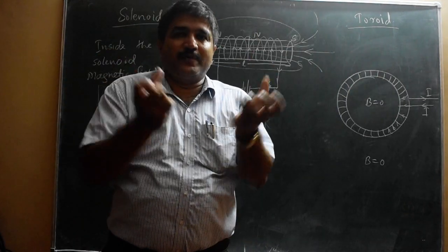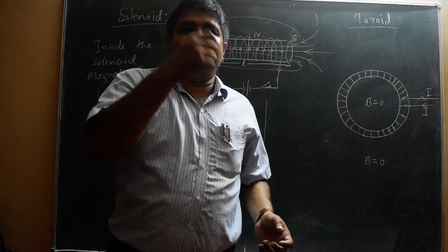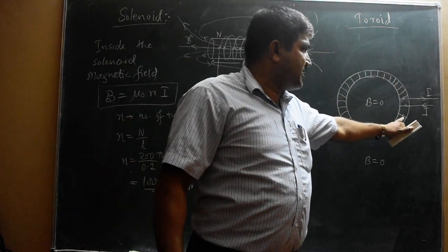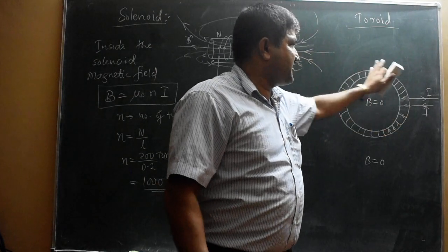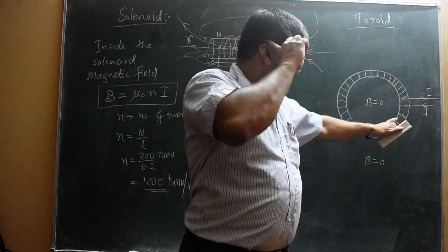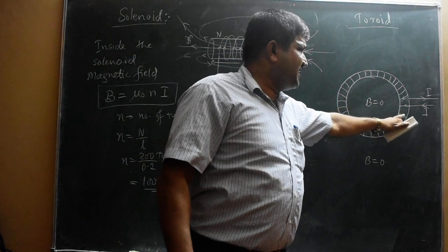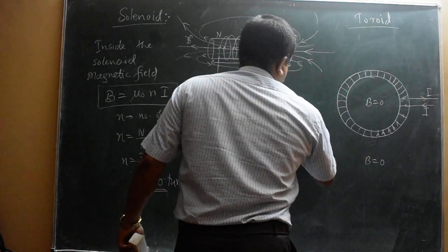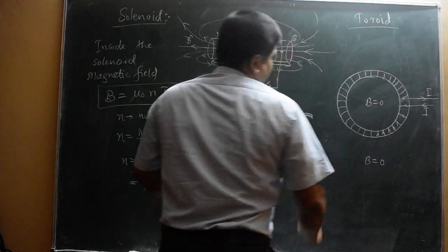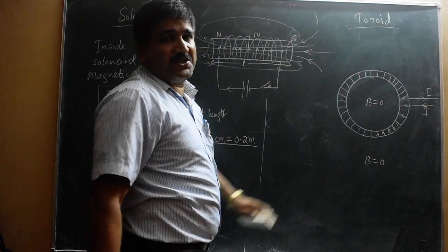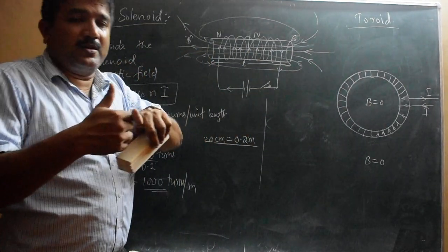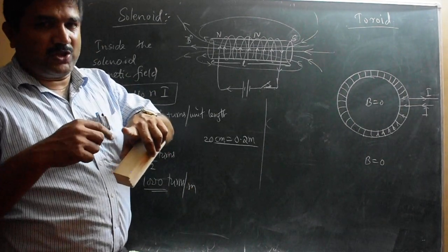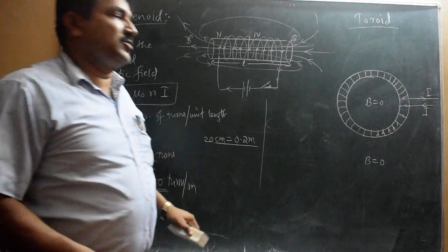So it is a tube ring-shaped object, and windings are made on the ring. Again, same here, insulated copper wire is wound very closely. Here space is shown, but it is not necessary actually. It is just to represent the current, and I made the space. The windings are one over the other like this. They are very close windings, both in the solenoid as well as the toroid. They are physically in contact, but there is no electrical connection from one turn to another turn. Current does not flow directly across; it flows through the length of the wire.